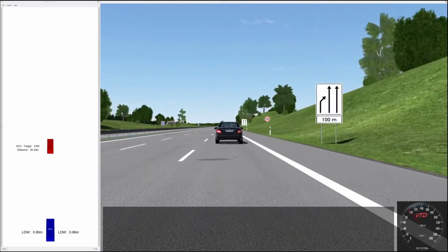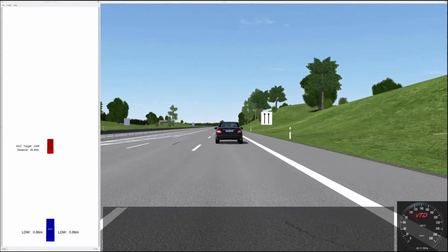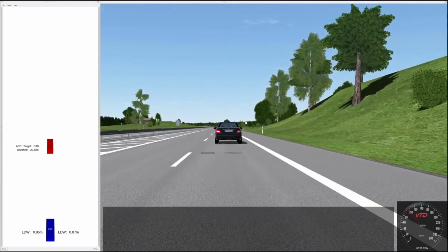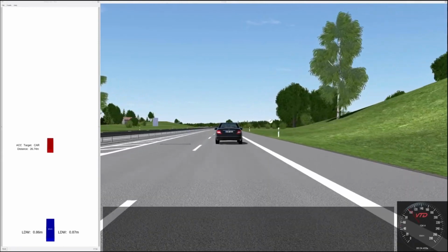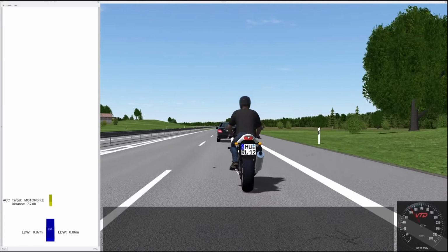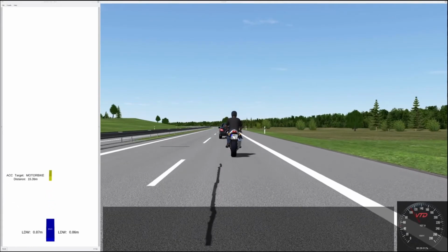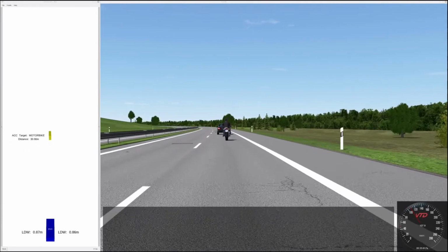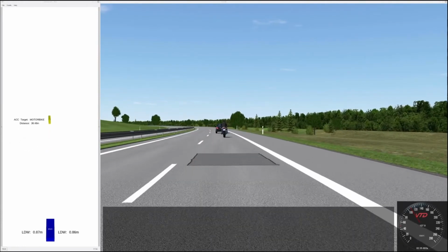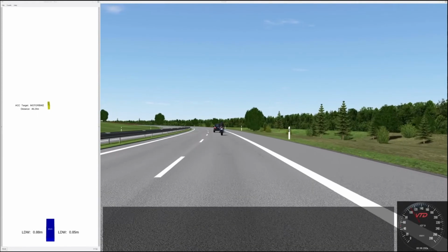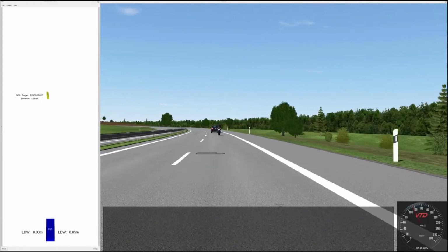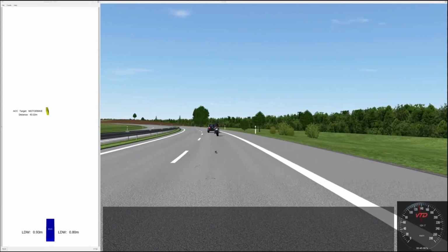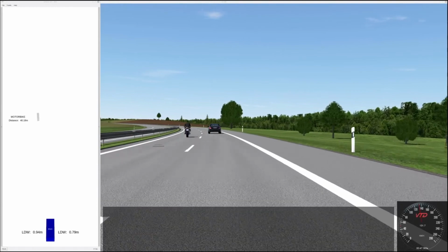As shown, the ECU model correctly identifies the object and triggers the ACC function when the object is in front of the vehicle. For the next test, the ACC model correctly re-identifies another object that arrives in the FOV as the ACC target object, despite a changing test scenario on a curved road. When the motorcycle changes lanes, the ACC model correctly re-identifies the car as the ACC object until the vehicle lane change occurs.